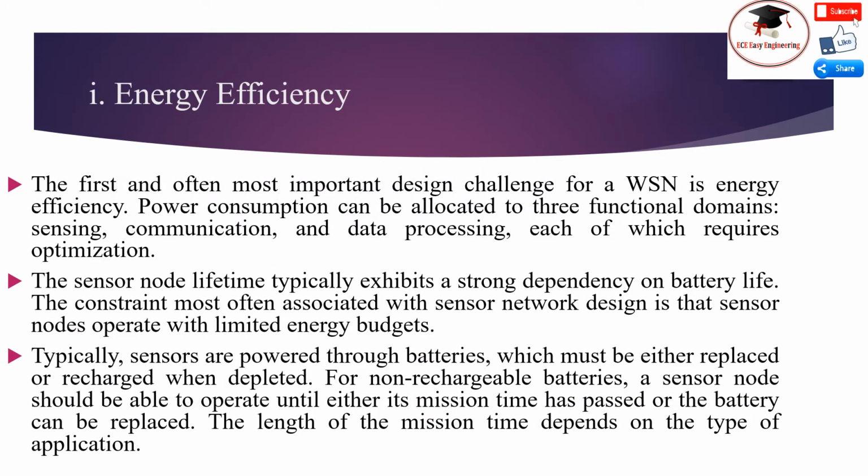First is the energy efficiency. The first and often most important design challenge for WSN is energy efficiency. Power consumption can be allocated to three functional domains: sensing, communication, and data processing, each of which requires optimization. The sensor node lifetime typically exhibits a strong dependency on battery life. The constraint most often associated with sensor network design is that sensor nodes operate with limited energy budget.